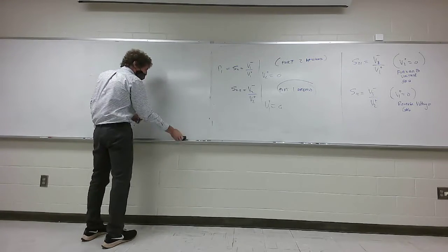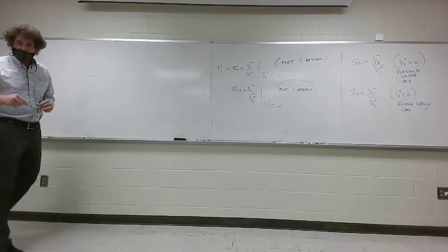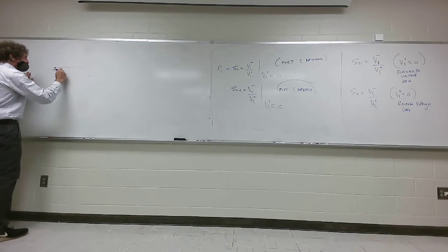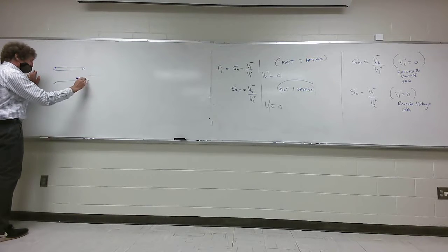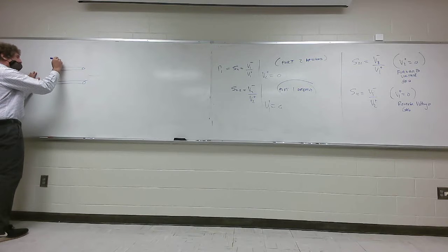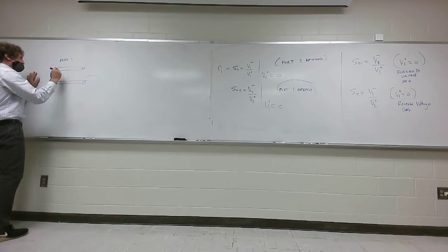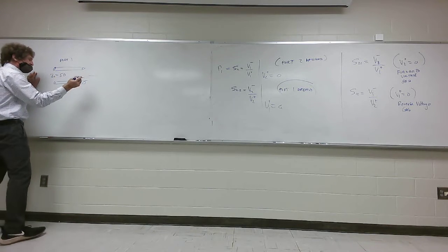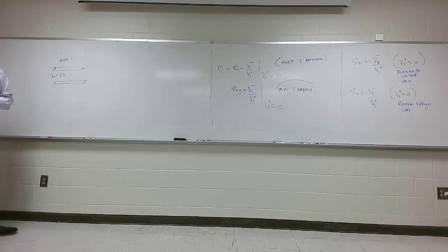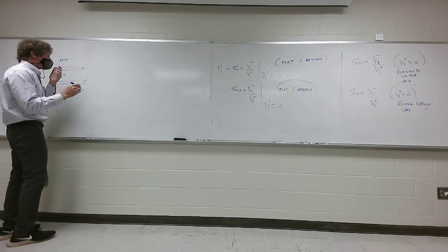So remember, what we want is the S parameters of this system. Here's the system. It's going to be just a coaxial cable, or a transmission line, say. Z naught on port 1 is going to be 50 ohms. Then right here, I'm going to put some lumped elements. These are resistors, capacitors, or inductors, and they're viewed only as the lumped element.